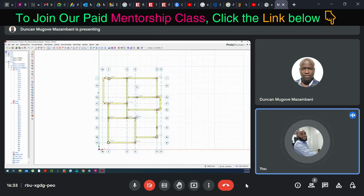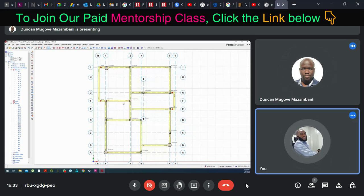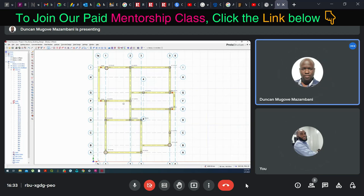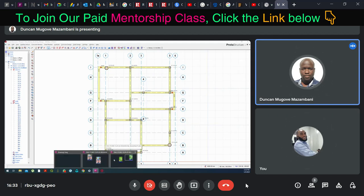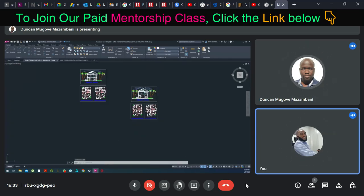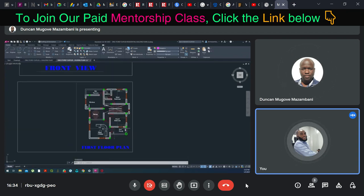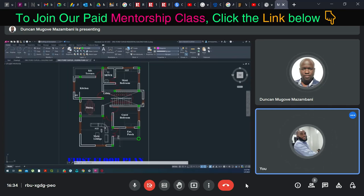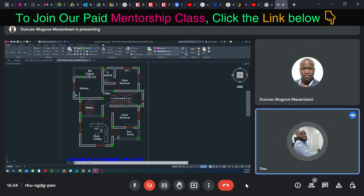Now also, sorry, come back. That circular column, change it. Go back to your AutoCAD and see that there is no circular column going upward. Not that one, the one that has our GA. Now you can see that on this first floor, we have only one circular column going up, and the two circular columns are not going up, right? So take off the two circular columns and change them to rectangular columns.